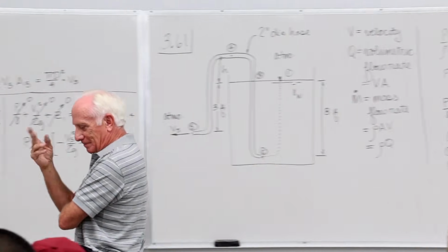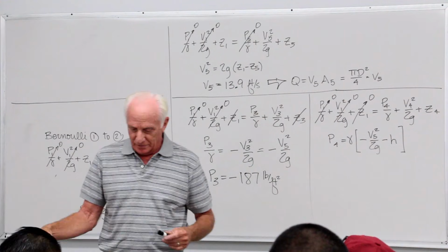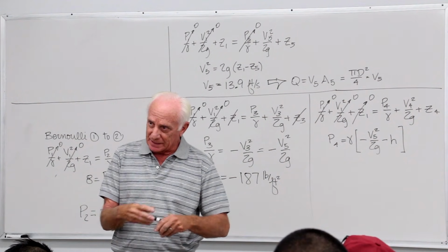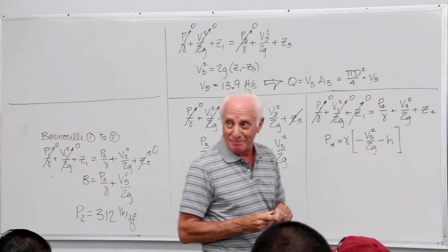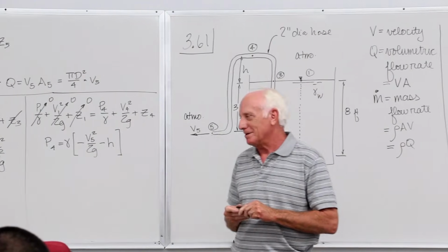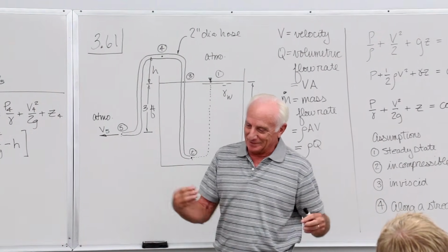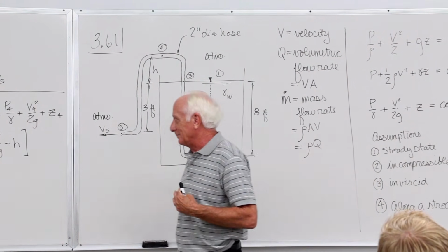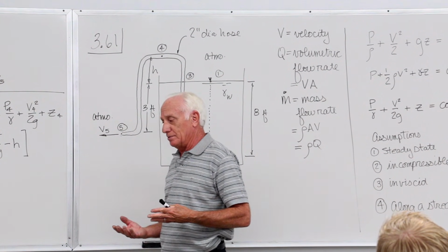Oh, it'll come out of there. Now, sometimes in a pump that draws water in, if there's a leak on the inlet side, then air might be sucked in because the pressure's below atmospheric. So sometimes the fluid comes out, other times the gas comes in. So that's negative pressure. What's the absolute pressure?